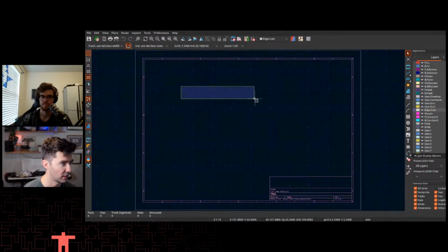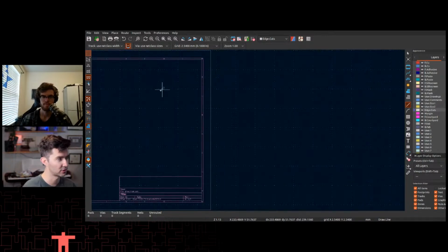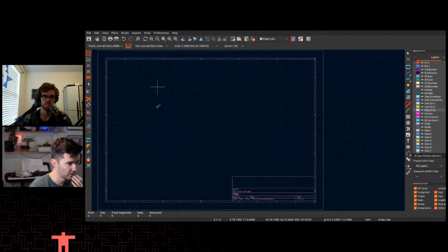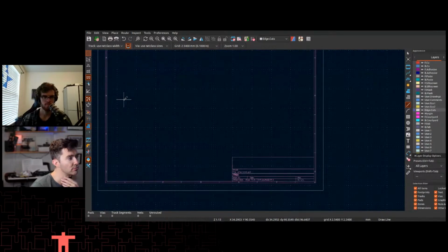So you have to select the line, near the edge cuts layer. This one. Yeah. So now you can just start to make a closed shape. If you zoom in a little bit, you could also see that there's dots on the screen, and you can just scroll to zoom. Yeah, it is actually not liking my.